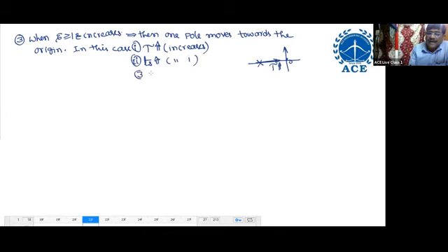Third, damped oscillations become 0 because it is on the real axis now. There is no more damped oscillation. The system does not have any oscillations when zeta is greater than or equal to 1. The system has oscillations only when zeta is greater than 0 and less than 1. In case zeta is greater than 1 and increases, the system has no more oscillations. Omega d becomes 0. And the system becomes less relatively stable.